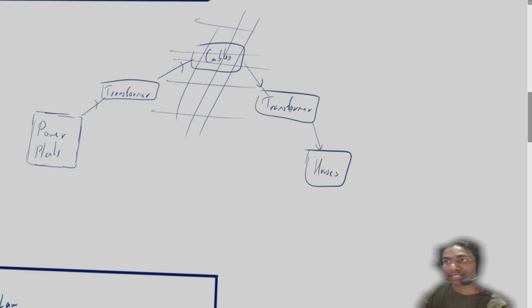What you should know is that when the power plants produce electricity, they are producing power at a really high current and a low amount of voltage, okay? Which is still fine, because remember from the equation, power depends on voltage times current. So it doesn't really matter if you increase or decrease one. But the issue is that if you cause a high amount of current to flow through a wire for a very long time, as in the case of the filament bulb that we discussed earlier, which was heating up, it's going to cause the cables here to heat up.